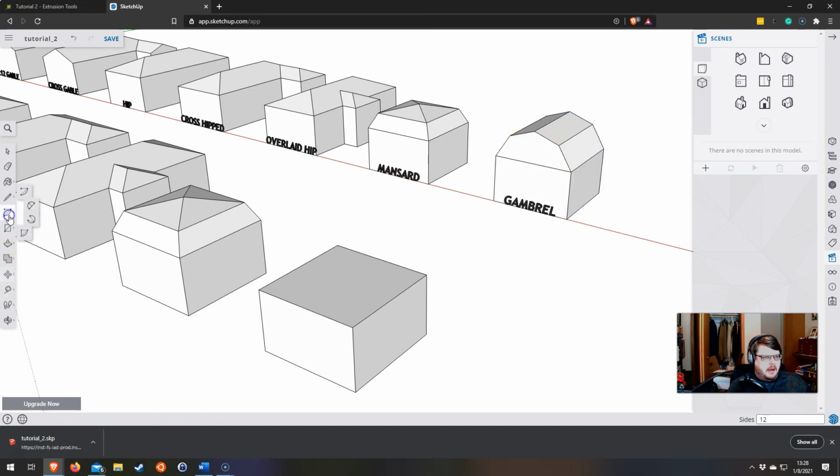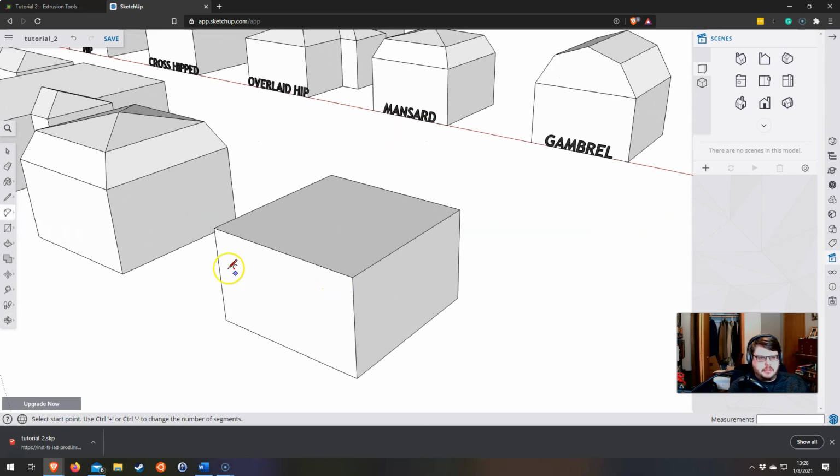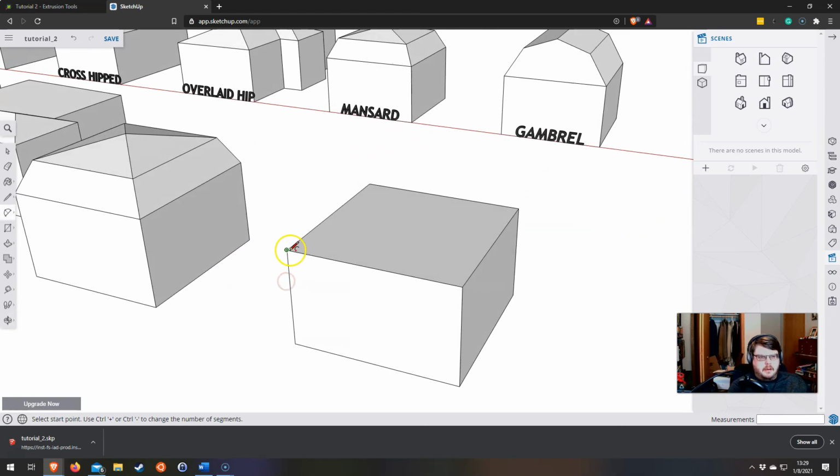We're going to use the arc tool. So we want the 3-point arc right here, not this. The default one, I'm not really sure why, I hardly ever use it. This one, the 3-point arc, is much more useful. So what we'll do is click here to start the arc, and then we'll click here, and then we'll go in the vertical axis. We'll constrain to the vertical axis by pushing up, and then we'll infer over to here.